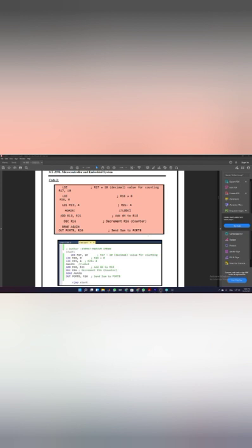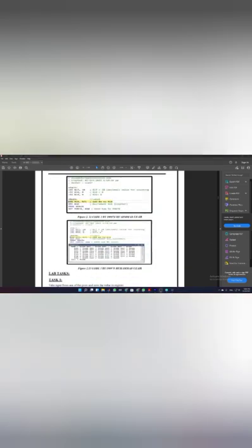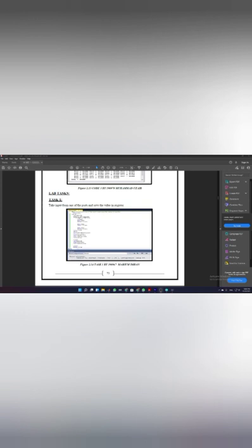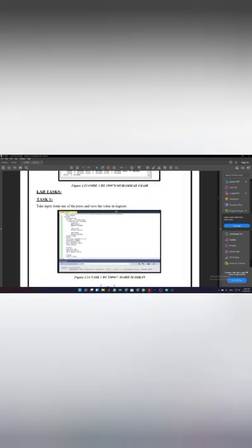code 3. In here you can see that the R17 register is loaded with the value 10, that is the decimal one, and then here you can see that R18 is loaded with a 0, and then R19 with 4. Again you can see that R18 and 21, and then decimal 16, and the BRNE command just tells us that if the branch is not equal, it will jump to the again loop, and then output b equals 20, meaning that port B is loaded with the value 20.